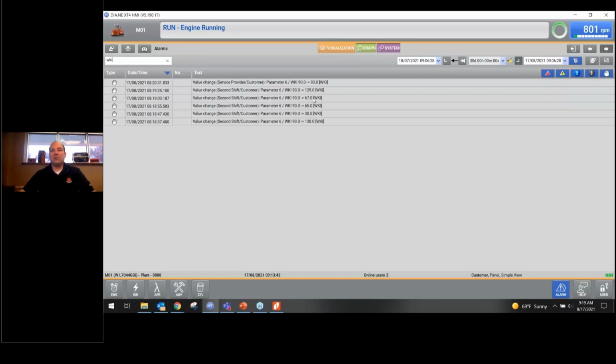Then they're going to start swinging around here, and they're going to say, well, I think it's close to 65, but I'm not sure, so I'll just keep playing a little here, a little there. That's not a recommended method either. So just understand, we really still want you to get a very valid fuel sample in order to properly set the control system. Again, there's a lot of stuff behind the scenes for how we adjust actuators, as well as timing curves and our fuel system, based on what fuel you're telling us to run. So again, fuel samples are really important pieces for us to use.